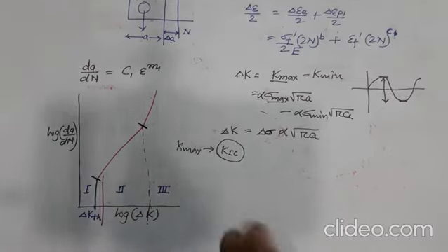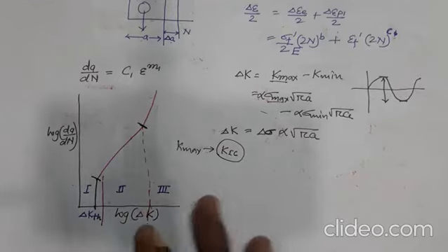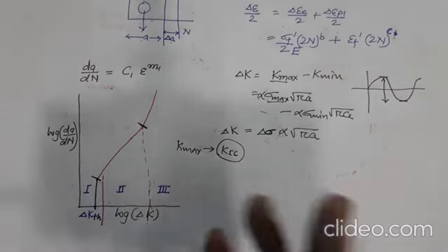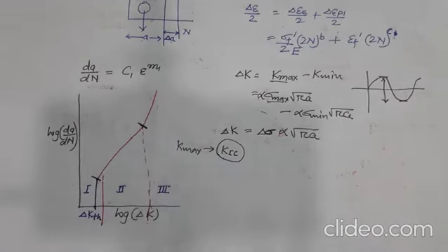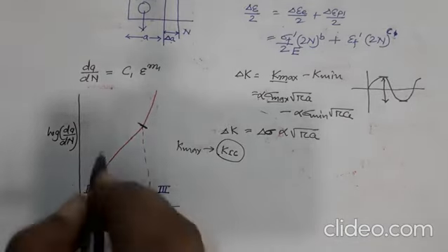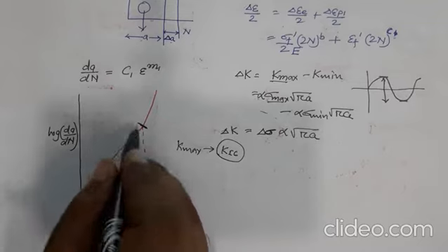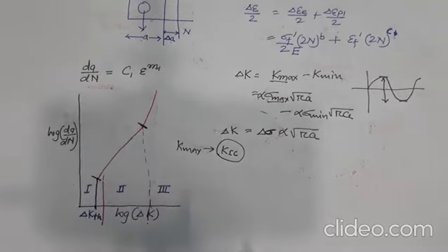And because the rail track undergoes a lot of fatigue cycles, as and when the train moves over it, you apply a load, and when the train has passed, the load is taken away. So it reaches zero stress. So we are applying a cyclic loading on the rails, and there, once we find out that there is a crack, we do have some time to replace it.